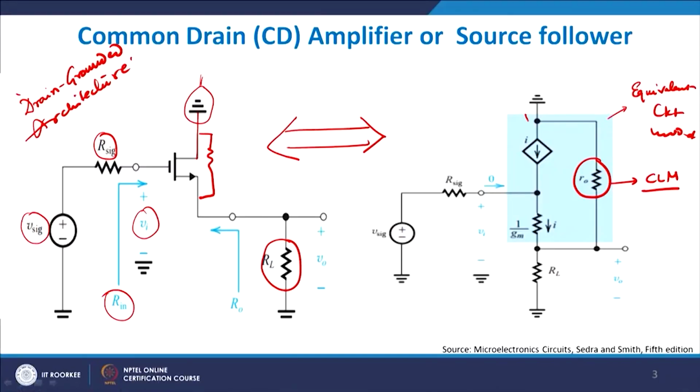and the source. So, this is your drain end, this is your source end, and this is your gate end. You will automatically have an impedance or a resistance between drain and source, which you see in front of you, and therefore you get this thing. What is 1 by GM? 1 by GM is nothing but this device itself, because remember this is basically a VCCS, a voltage controlled current source. So, I can safely write down that